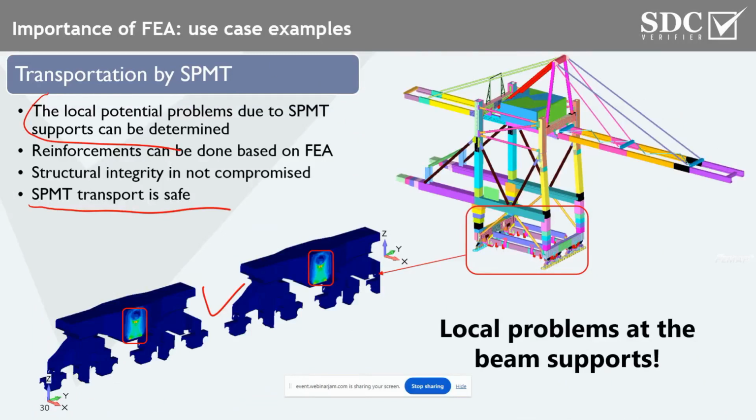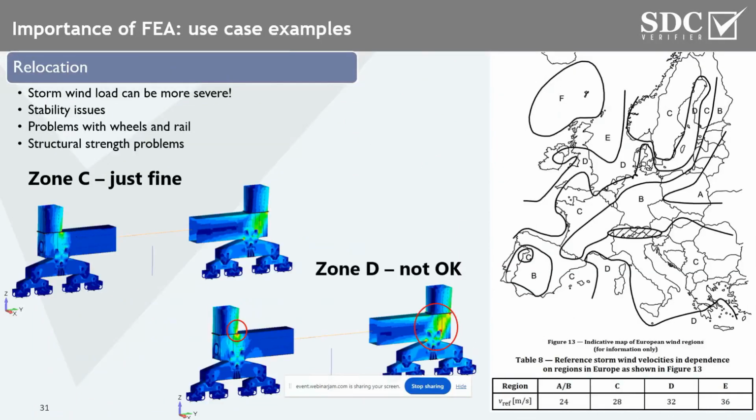I also decided to highlight one more important thing, in my opinion. So this is crane relocation, a simple relocation from one region to another one. So this is something normal, people buying the cranes and selling the cranes. However, crane relocation makes an influence on the operating conditions as well. Why? Because changing the location of the crane, we're also changing the wind zone, which is important at out of service conditions at storm. So basically these conditions can bring quite a lot of issues.